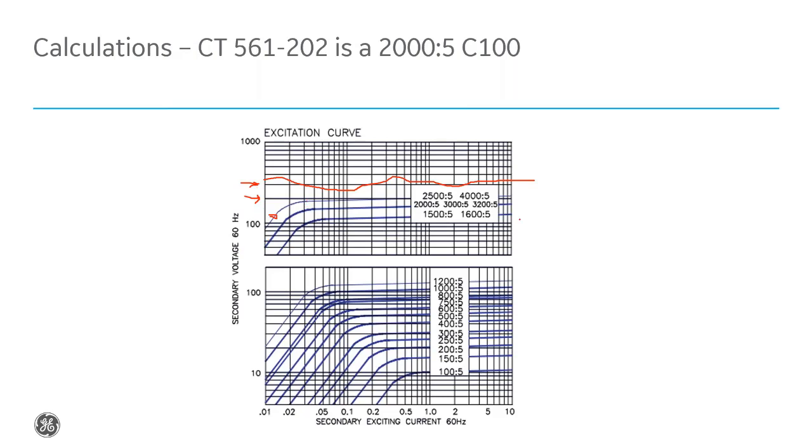Now, in this case, this thing probably is going to support about 200 volts. The knee point's here a little bit over that 150 volts. So we might be able to use that here with some caution, right? If we set it around 75 milliamps.